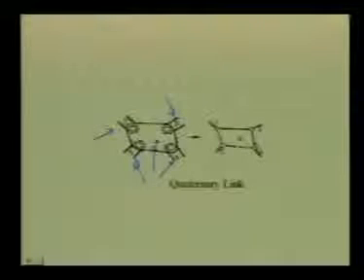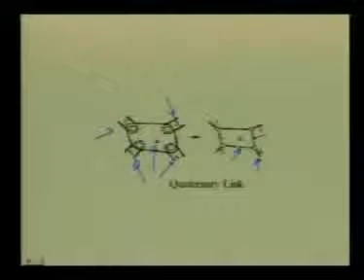One may interpret that at this revolute pair, 3 binary links, this one and link number 4 are being connected. To avoid this ambiguity, we should hatch this link number 6 to represent that this is a single rigid body and this is a quaternary link connected to 4 other links.